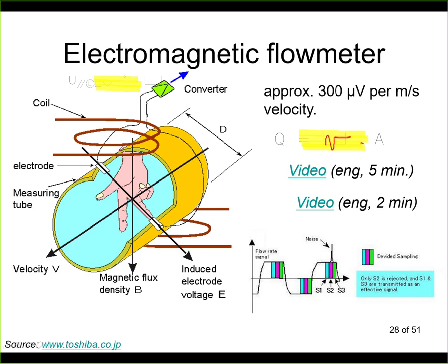When we then reverse the polarity of the magnetic field, we'll get this reaction, and those colored rectangles are the sampling intervals. So we sample multiple samples here, we sample multiple samples here, and we are trying to reject the eventual noise that we may see here, for example. So it's not a permanent magnetic field that could be created by a permanent magnet, but it's a variable magnetic field. So we maintain one polarity, one amplitude, we measure, we then switch the polarity, we measure again, and this will compensate the external magnetic fields because they will act like a DC component that we have in the measured data.